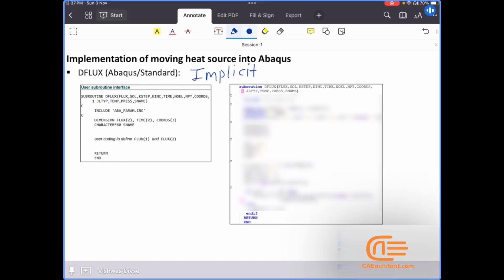And for such very fast wave propagation phenomena involving material non-linearity and contact non-linearity, engineers and scientists prefer the explicit method because that will converge your solution.